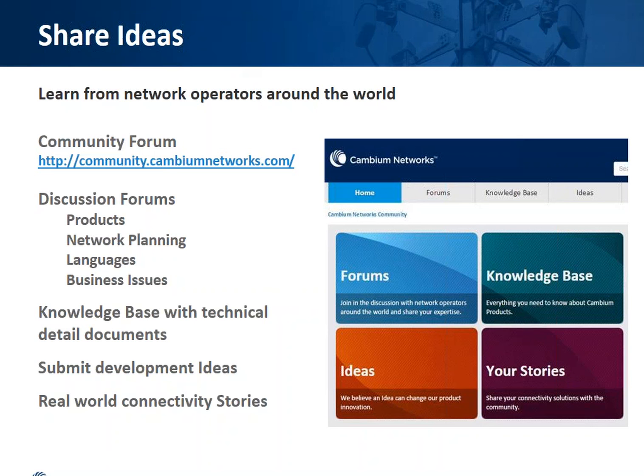That product uses an 8 meg channel, and so typically you have 3 channels available to you, and with our system of frequency reuse, if you're doing a 360-degree coverage, typically it's deployed as ABC, ABC, where you're reusing a frequency back-to-back. So you have 3 different frequencies, and typically it's 907, 915, and 924, or 922, something like that.